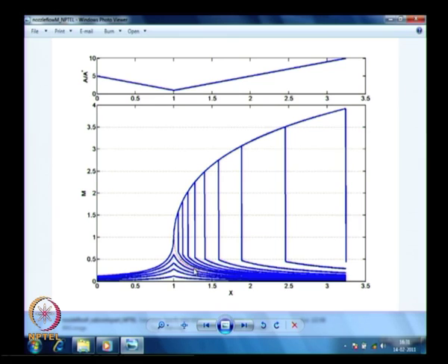That dotted red line is our P critical 1 pressure, P back, okay. Anything below that pressure, my Mach number increases, it goes supersonic, jumps across the shock to subsonic. So, you can see that M equal to 1 line is here, it is jumping across from there to here to subsonic, and then it is going subsonic solution, decreasing Mach number further.